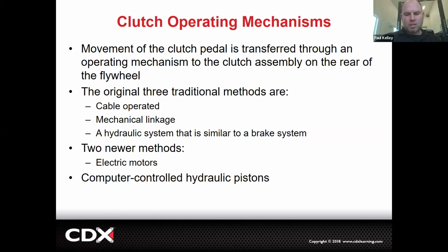it engages and disengages the clutches because there's two, an even gear clutch and an odd gear clutch. So in first, it's got the odd gear clutch engaged, right? Then it pre-shifts into second, but it doesn't connect that second gear shaft. And then when you want to go from first to second, it literally releases clutch one, releases the odd shaft and engages the even shaft clutch. And now you're in second. It pre-shifts into third, right? So it's kind of interesting.